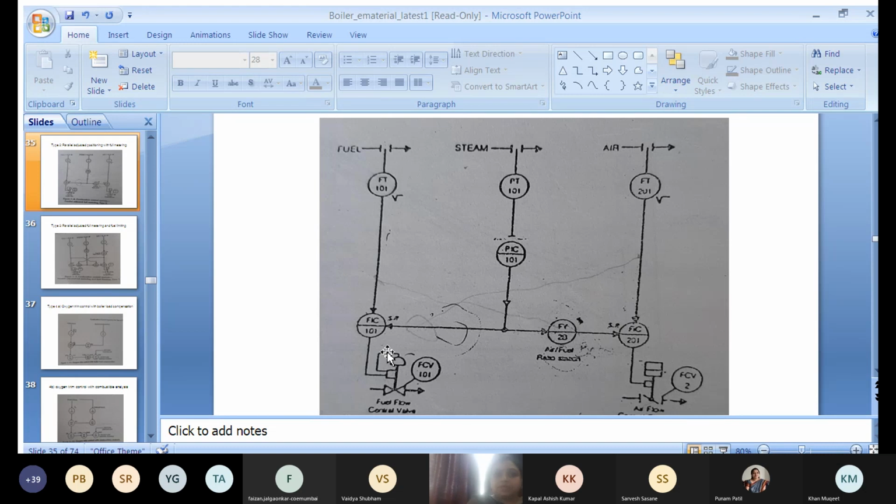So this control valve is with positioner. Now it is carrying the fuel. Why is it so important to stabilize the position? There should not be even a little leakage, otherwise because of vibration, if the stem position is not correct, it is not properly opened and closed, so it may cause leakage. But this control valve is used for boiler controls, right? Combustion control is on the fuel supply line, so the fuel supply line is a very critical control line. So we need to select the instruments and devices in such a way that they satisfy the need of that application. So our need is that tight shut off should be there, or accurate positioning of the stem should be there.